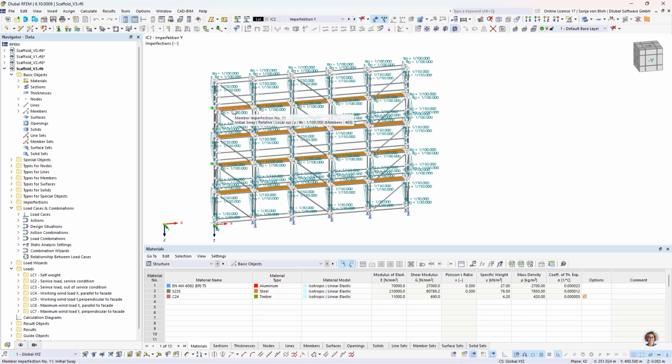I can now proceed to set up the necessary parameters for load combinations for the ultimate limit state according to EN 12811 Part 1. Partial safety factors of 1.5 must be applied to all permanent and variable actions. The load combination can be represented in RFEM using a user-defined load combination.